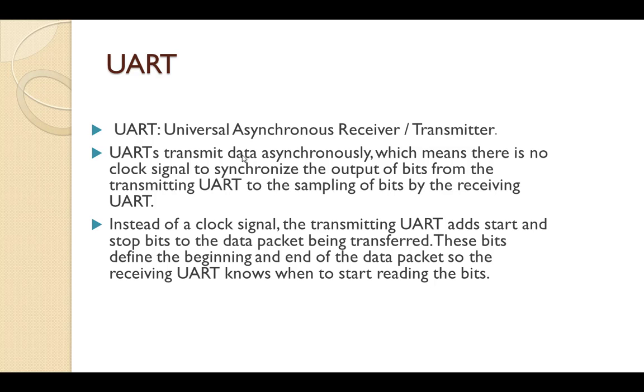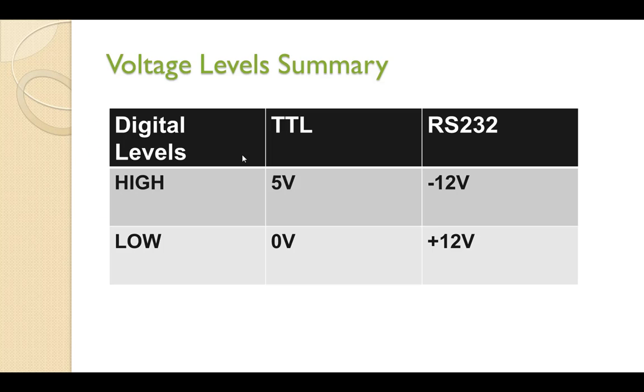On the receiving side also, the same thing happens. This is what I am trying to say here. Instead of a clock cycle, the transmitting UART adds a start and stop bit to the data packet being transferred. These bits define the beginning and end of the data packet, so the receiving UART knows when to start reading the bits, right?